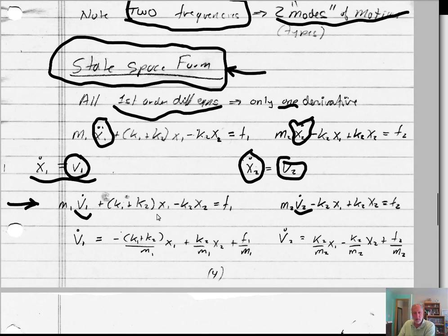But if we wanted to calculate position, which is included in here, we need to know, well, how is position related to velocity? Well, that's exactly these equations here, essentially the definition of v1 and v2. So what we've done is replace 2 second-order differential equations with 4 first-order. Here's the first one, here's the second one, the third one, and the fourth one. So we haven't really lost any information or changed anything. We've just renamed some of the variables to get it into this standard form that only has first-order derivatives.